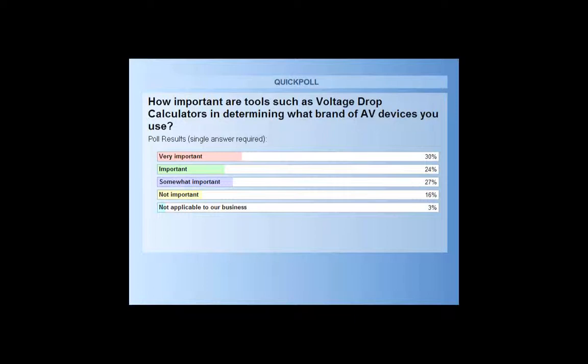Okay. There was a question about changing the power to the circuits in the volt drop calculator. Would that be a setting of the 1 amp versus 1.5 versus 2 amp? Right. When I was going through the demo, the default value for the panel power is 1 amp. You can adjust that all the way up to 15 amps. That field is an open field. You can put in 6.5 amps, 7 amps, all the way up to 15 amps. So we start at 1, but it is an open field that you can change depending on what you're using.